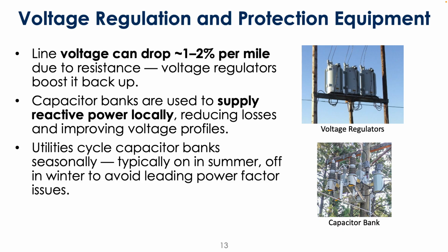Other things to help with power quality are capacitor banks to supply reactive power. These can change in the way that they're utilized depending on the season, because it affects power factor issues.